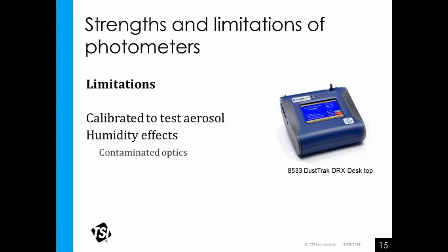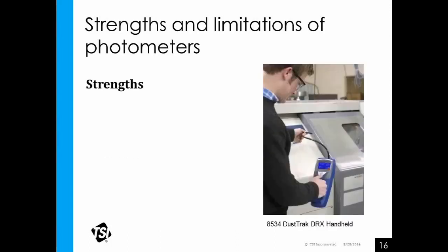Get rid of the big stuff, manage that. Use the photometer to measure areas where the aerosol is lighter, where you don't see it, where what are we being exposed to, the small stuff that could be breathed in deeply. If there are areas outside where instruments need to be, we've encouraged people to use a PM10 impactor that's going to cut out the big stuff that will plug up the instrument. That way the small stuff still gets in, you're still getting those readings. But that is a limitation of the instruments. They will eventually load up and need to be cleaned out in high concentration atmospheres. So there are some limitations, but there are also a lot of strengths.